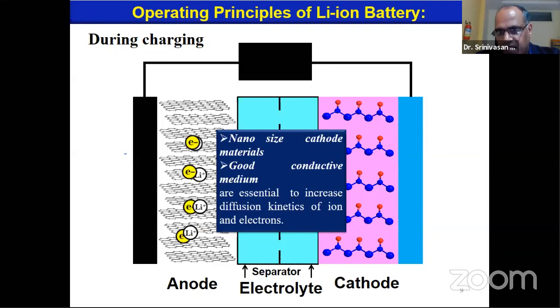But the advantage of the supercapacitor is that wherever you need high power, for power backup whenever there is a power shutdown, you can use it, and it comes with nearly 1 million cycle lifetime. Because when you do an electrochemical reaction in the battery, there may be some degradation. But when a physical phenomenon is involved in the mechanism, there is not much change in the electrode. That is the reason it comes to nearly 1 million cycles. It means 10 lakh cycle lifetime.